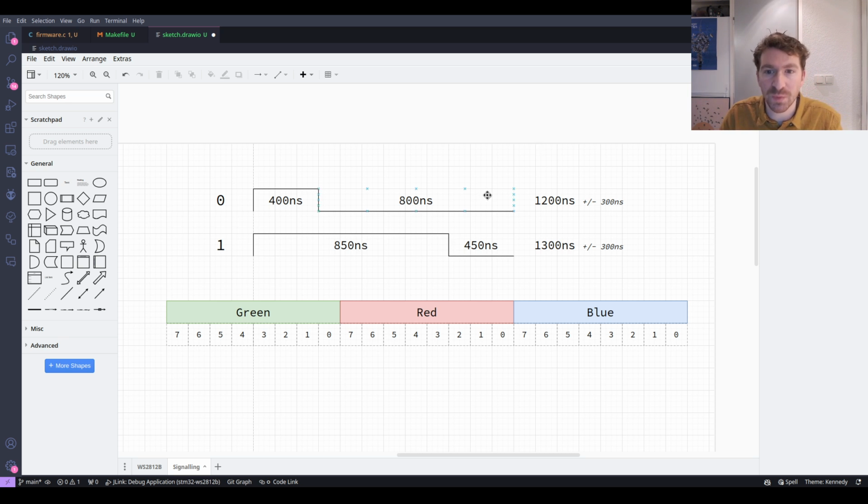That's one possible approach. Now there's another thing to think about, which is if you're the other device. I talked about this being a self-clocking signal. Well, we can understand how long we need to watch these signals for, but also the fact that the line goes high and then goes low. We do have to do some counting, because it goes low for 800 nanoseconds here, and we need to count how long it was high for.